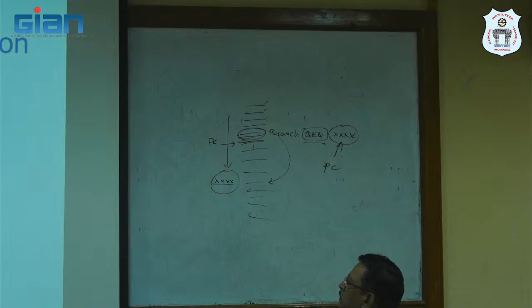If the result is 0, the branch goes to the control logic, that means the two register values are equal, and it branches to the new address. Otherwise, the current address is PC plus 4 from the instruction data path, and the new address is indicated from the instruction template.